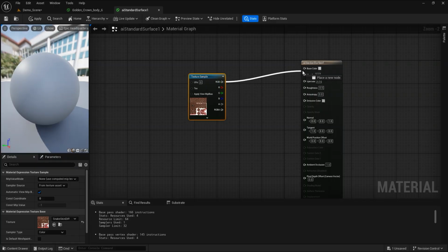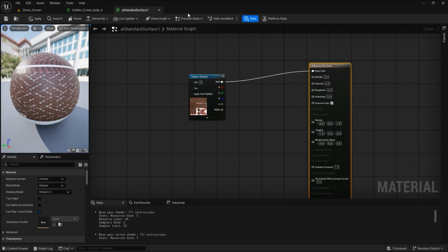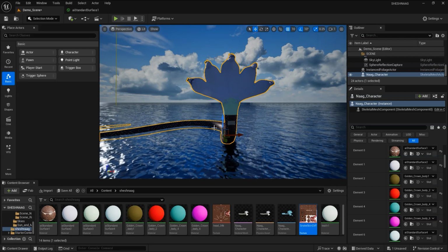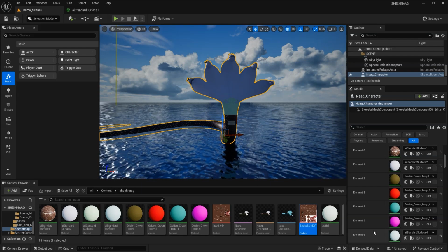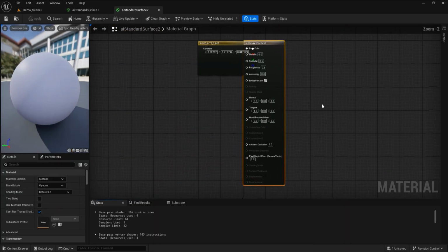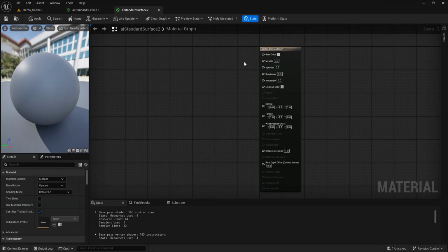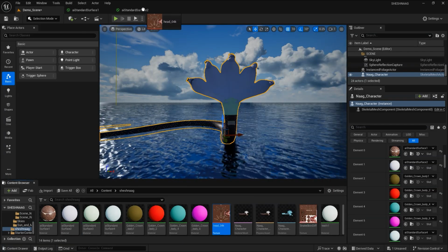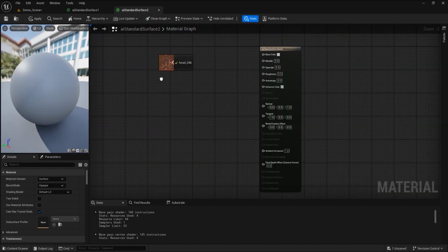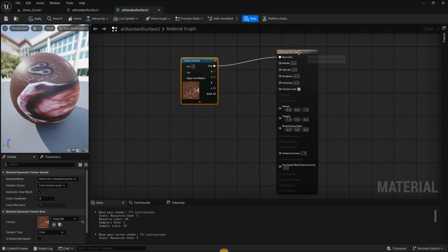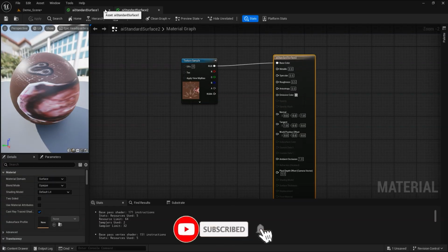So now we need to check whether bump or normal maps are there or not. So we need to check those things. So just close it. Yes, now we can see here this is the texture. And one more material we have to check, which is this, right? Double click and go back, delete it. Now get this file back to here. So now everything is ready.